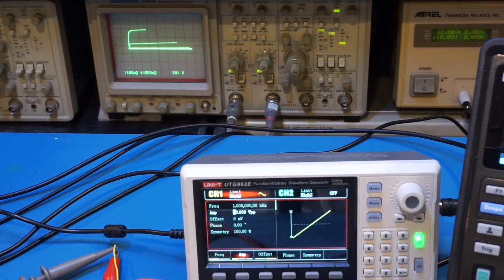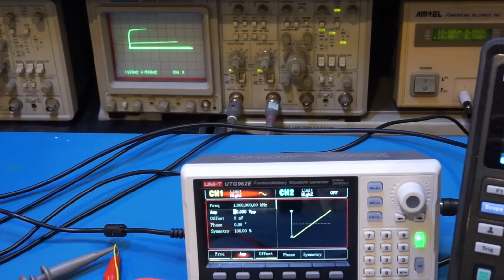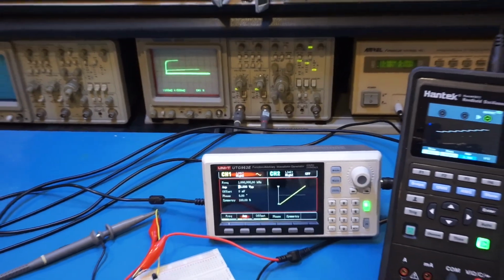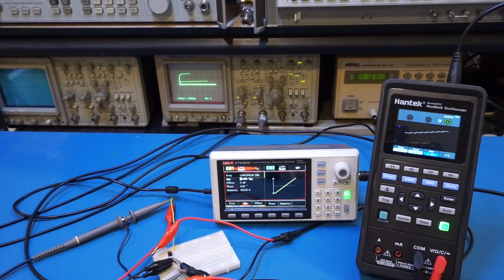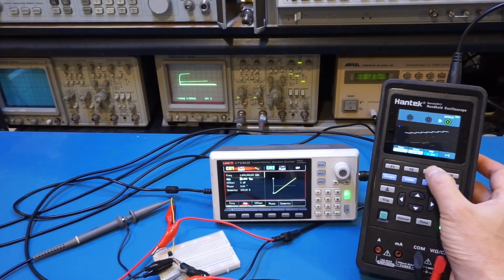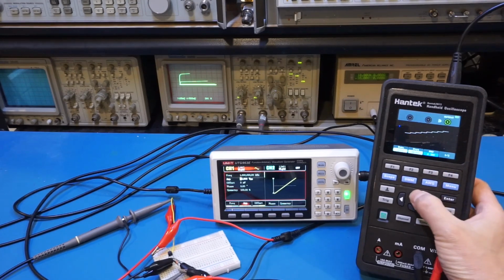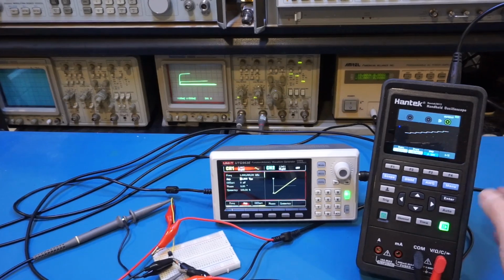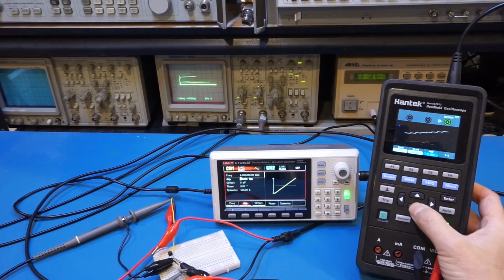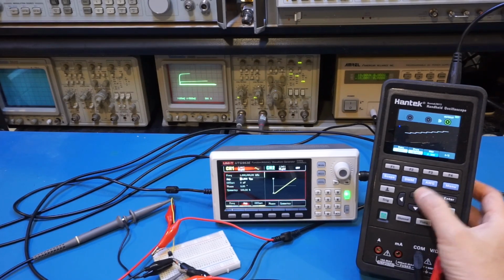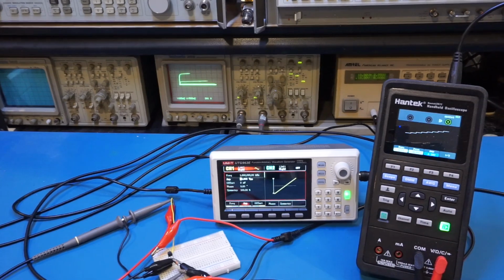Unfortunately, as you can see on the scope here, we only have a few lines there. That's because we have some limitations on the output voltage from the Handtech signal generator. Right now you can see that the amplitude output is pegged at 2.5 volts, and that's actually the maximum we can generate from this signal generator. And if we reduce that output, you can see that we have even fewer lines to work with. So that is the limitation of this signal generator.